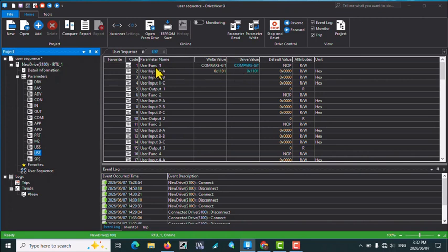Here, the function we've selected, you see that GT stands for greater than. To set up input A to assign its value, you can see that in the USF group, parameter number 2 is for input A, number 3 is for B, and number 4 is for C. In the greater than function, we said that if A is greater than B, whatever value we have in C will be sent to the output.